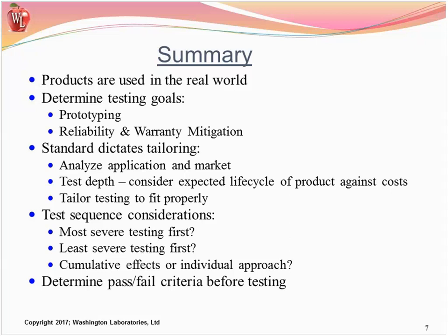And your pass-fail criteria, you should spend as much time looking at that and determining what is going to count as a pass, what is going to count as a fail, as you do determining the particular test and details of those tests to be done, because it's just as important as those tests. If you run a test and you can't really say whether the unit passed or failed, it had some issues, maybe it didn't work, but after it was taken off and some stuff was put back together, it did, that can really complicate test plans.